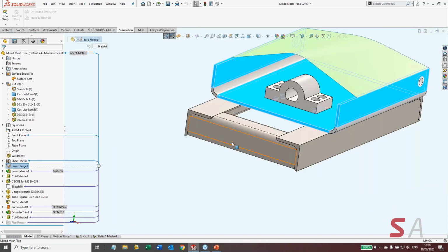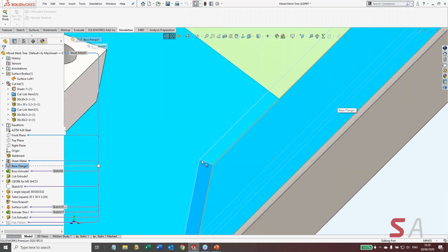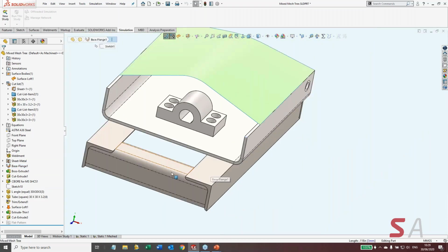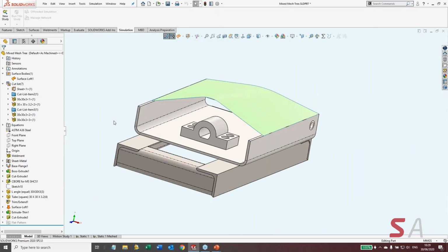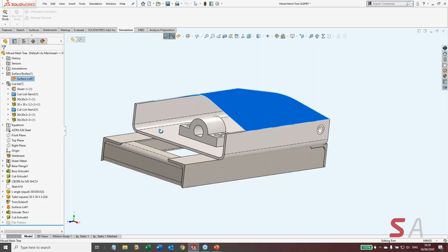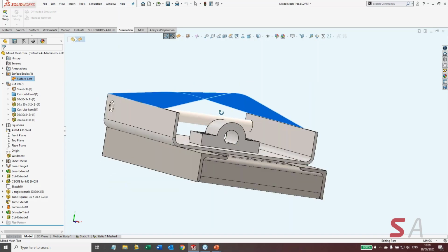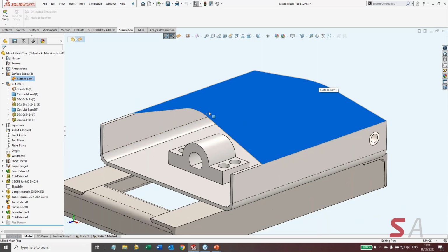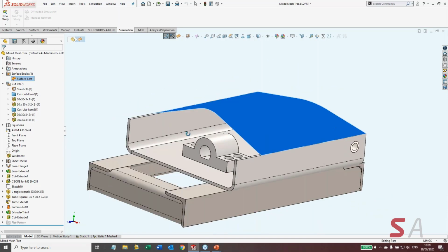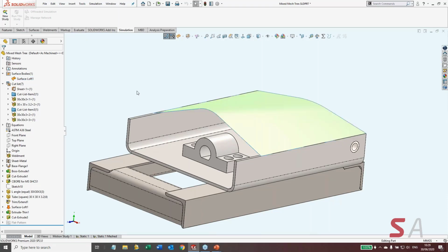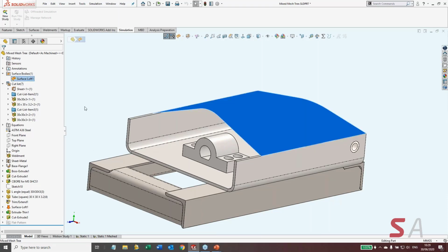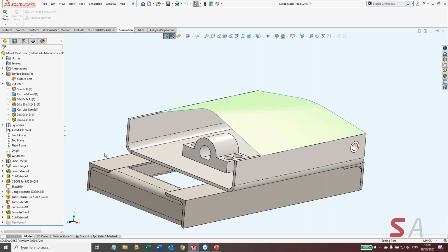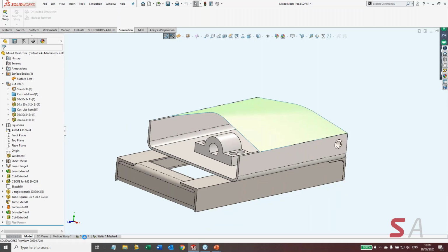So that's sheet metal of a thickness of, how thick is that? That is 3 millimeters thick. And so that's a sheet metal body. We know that's going to come into the study as a shell. And then I modeled a surface loft. I wanted to model something with a little bit of shape complexity. Sheet metal, you could do that in sheet metal, but it models a little more easily as just a thin, infinitely thin shell model. So that's what we've got in our 3D CAD model.